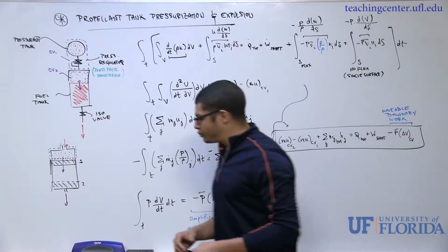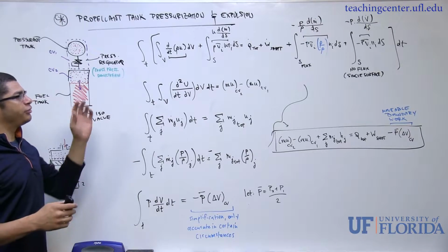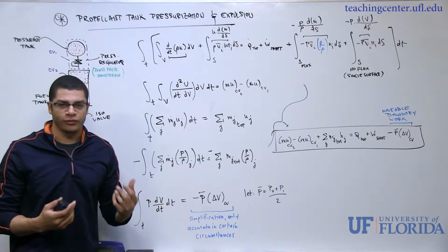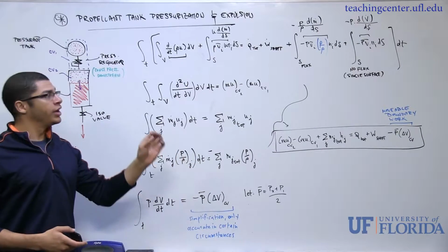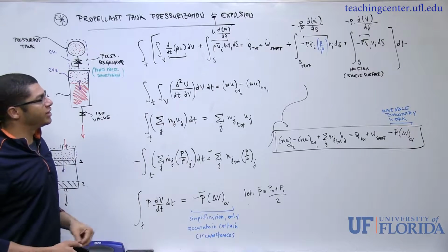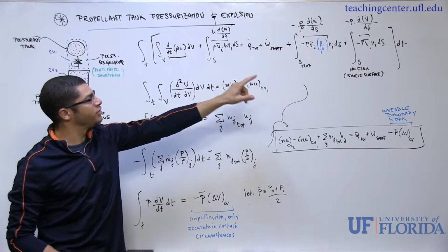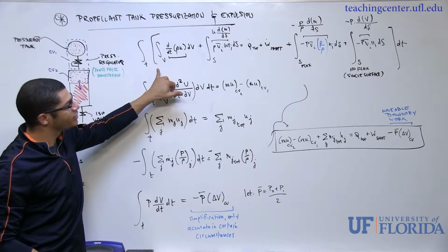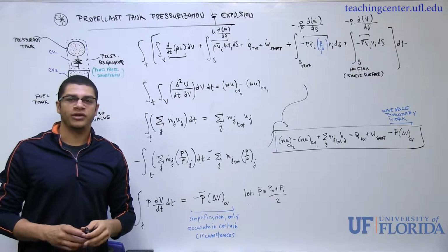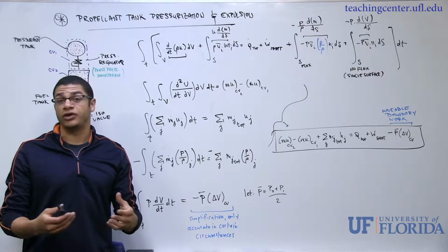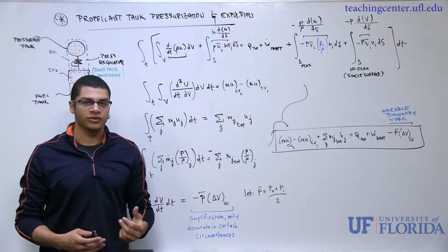So moving over to the right-hand side, what I have up here looks pretty fancy. It doesn't really look like our typical form of the first law, dU equals delta Q plus or minus delta W. But it really is. It's just in disguise. If we neglect this integral outside and the dt down there and just look at what's in brackets, really that's the first law. And if you're unfamiliar with this, please see the video on the derivation of enthalpy and its use with open systems with the first law of thermodynamics.